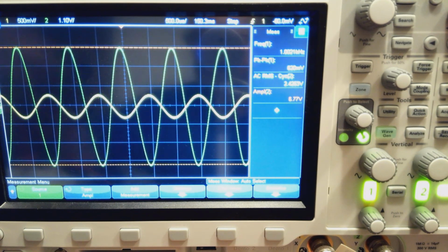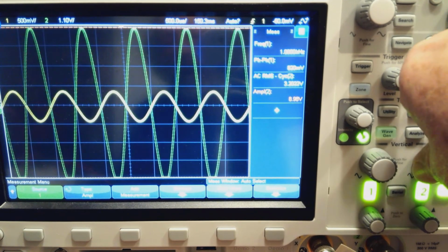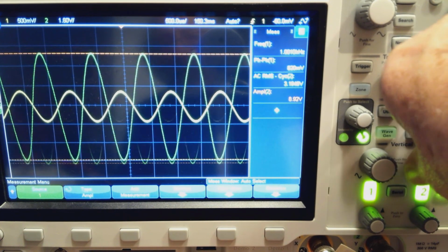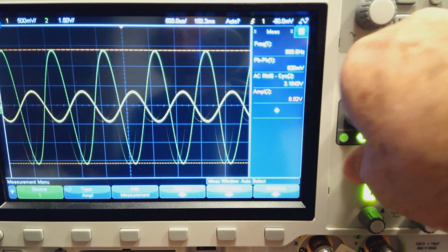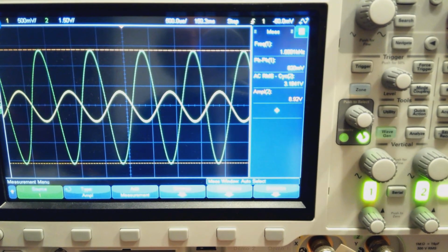Let's go up to 800 for the input. Go to 800, hit the scope, and again now we're starting to get, so I'm going to drop this down to, let's make this 1.5, and yeah, we should be able to stop it there. So now we take a look, and we have about 800 millivolts for the input peak to peak and about 8.9 volts for the output.